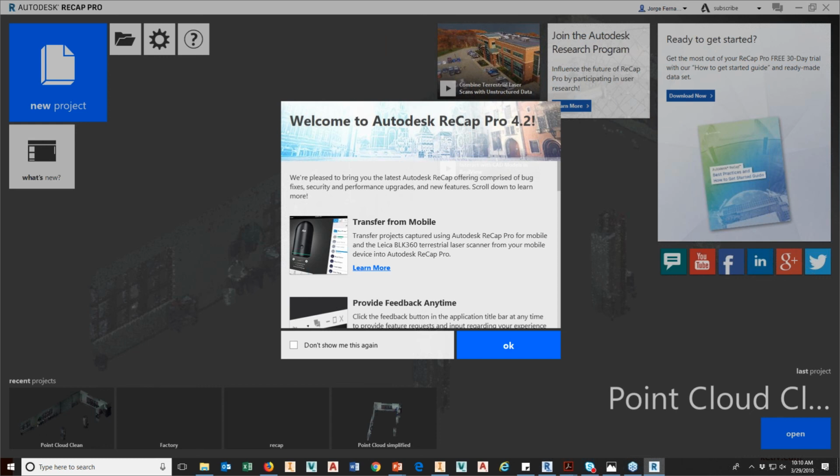Right now, what you're about to see, the example I'm going to show you, is part of what you get through ReCap. So if you're a suite customer, you have this capability. And it's to be able to bring in point cloud data. So that's someone going out to a site, creating a scan by bringing out a laser scanner, and then you're able to bring in that information. Now, when you bring that information in, you're getting an as-built. You might not need all the information, so you can actually come in here and modify it.